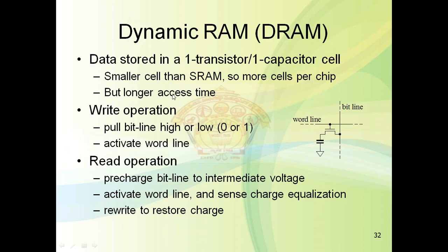but it requires longer access time, meaning read-write operations will take more time. So we'll see how the write operation and read operation are done. For the write operation, we have to store the data onto these capacitors, that is, we have to store charge onto these capacitors.